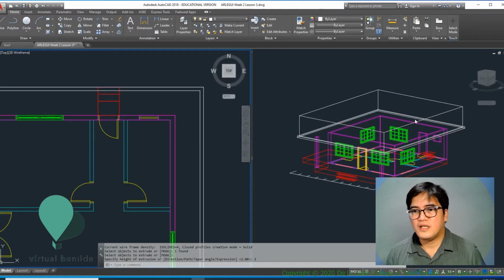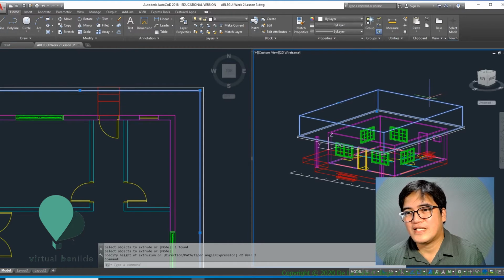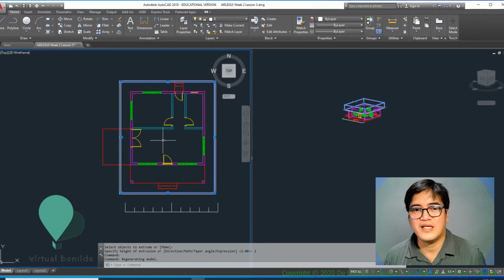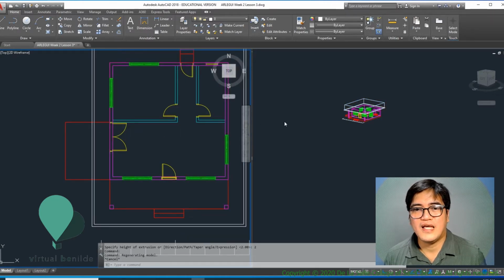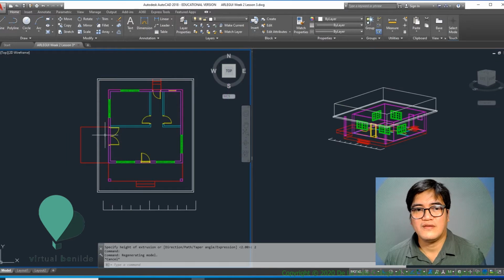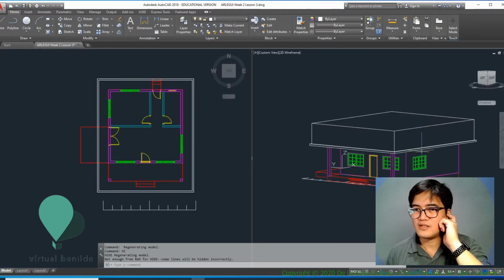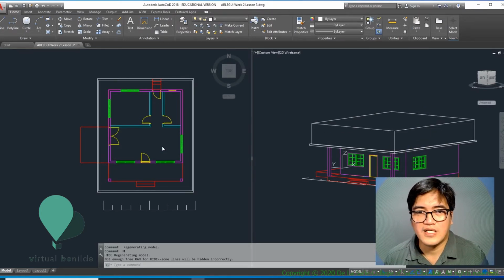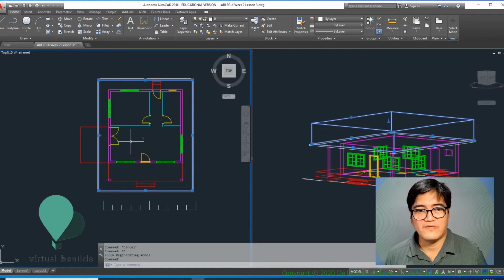Now I'm going to be doing a bit of slicing here. Slicing meaning we're going to be slicing this solid like, let's just think about it as a knife. So we can do the first half of this so that it's not so complicated. I'm going to slice this over like half of it. Okay, I'm going to click onto this object, of course the solid one, the box. This is what it looks like. So we need to kind of sculpt it into looking like a gable roof that we need. I'm going to slice it halfway.